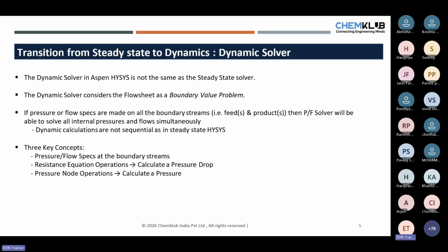Similarly in dynamics, you study these nodes and develop the dynamic model. It need not be a complete plant-wide simulation, otherwise you will be lost. Dynamic simulations are very specific and have a very specific purpose. You analyze that node, replicate it with all the minor details, and then study the transient behavior within that particular boundary limit. That is why the boundary conditions must be defined properly.